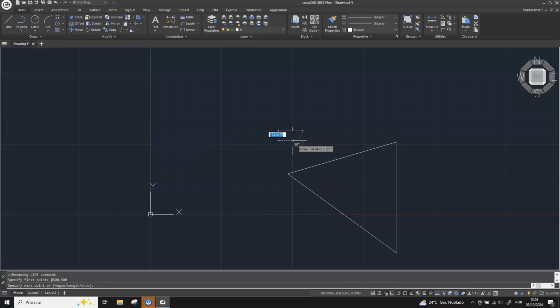Depending on our settings, you may have noticed that the dynamic input will display the line angle while you are drawing it. This is another variable we can account for while drawing the lines, so let's say for example we want to input both the line length and the angle with which it is drawn. Let's start our line command to choose a point. Next, when we are asked to choose the next point, we stop.